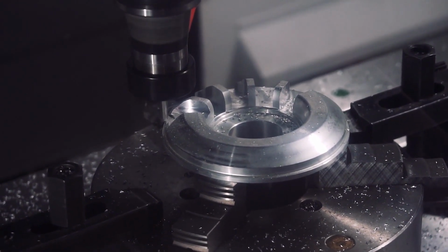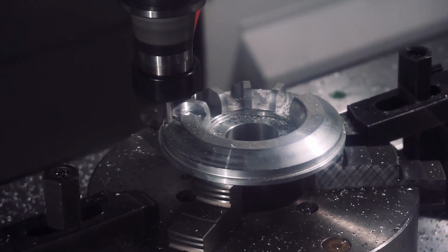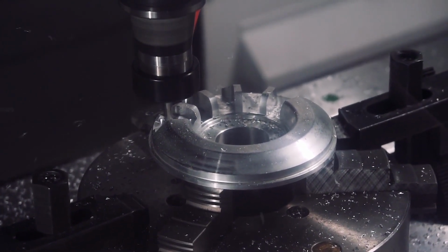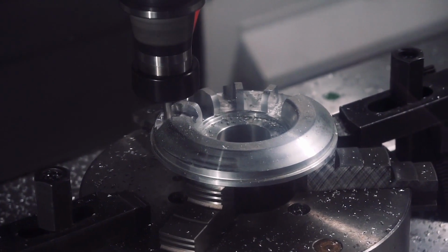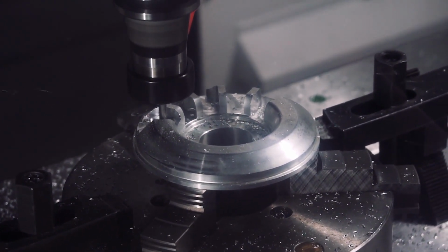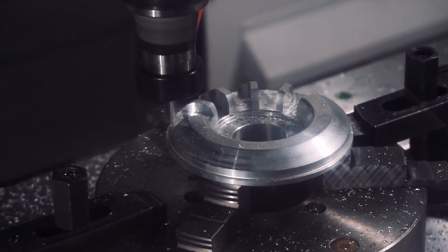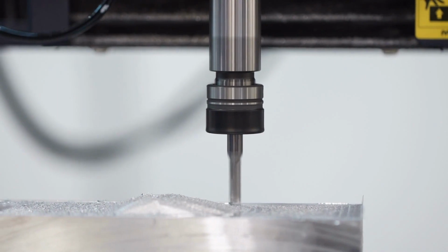Tool offsets. It's pretty common to use multiple tools for the same job, but you need a way to account for different tool lengths. Programming tool offsets into your CNC machine makes this easy work. With a tool offset programmed, your CNC machine will know exactly how far each tool extends from the spindle. There are several ways to record a tool offset.